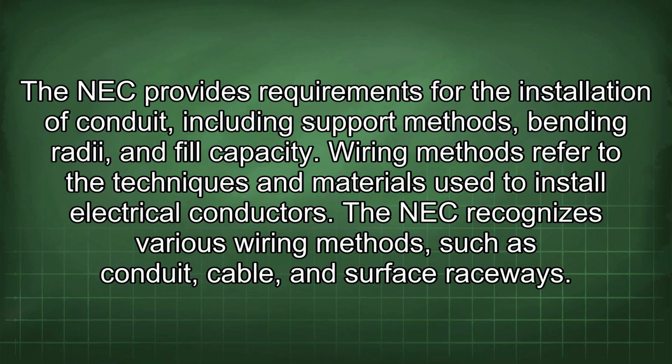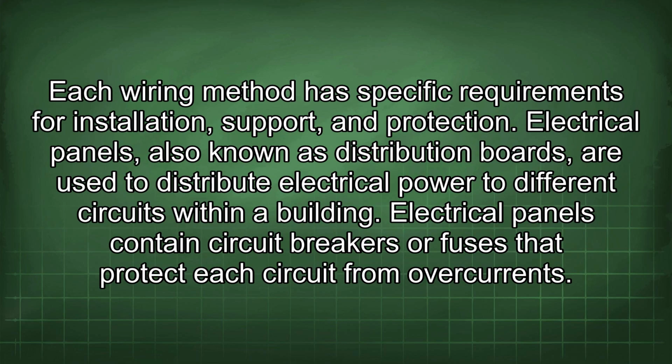Wiring methods refer to the techniques and materials used to install electrical conductors. The NEC recognizes various wiring methods such as conduit, cable, and surface raceways. Each wiring method has specific requirements for installation, support, and protection.